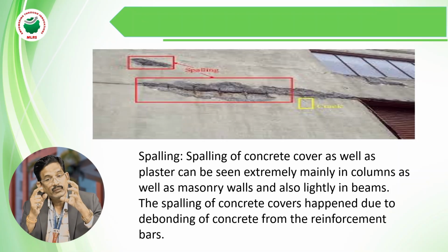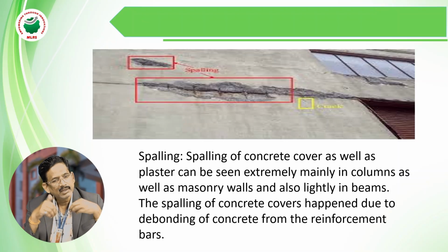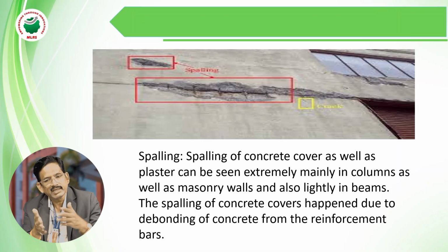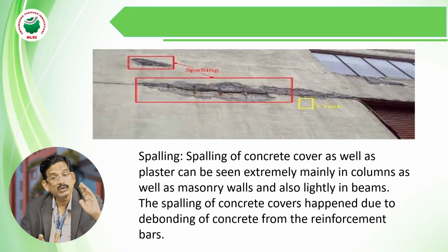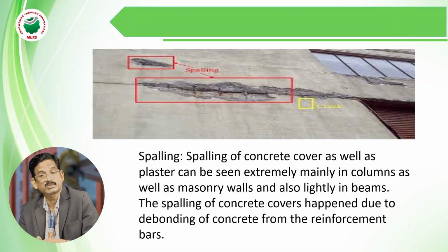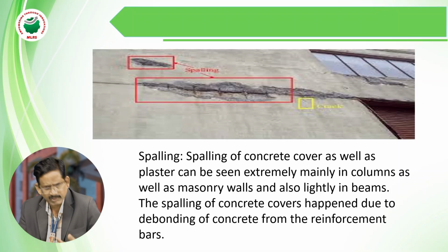So that's why we are using steel as a reinforcement, and for getting the compressive strength, we are using the concrete. Concrete is a heterogeneous material, steel is a homogeneous material. Steel is only a single material, whereas concrete has cement, fine aggregate, coarse aggregate, water, admixtures and any other substitute materials also.